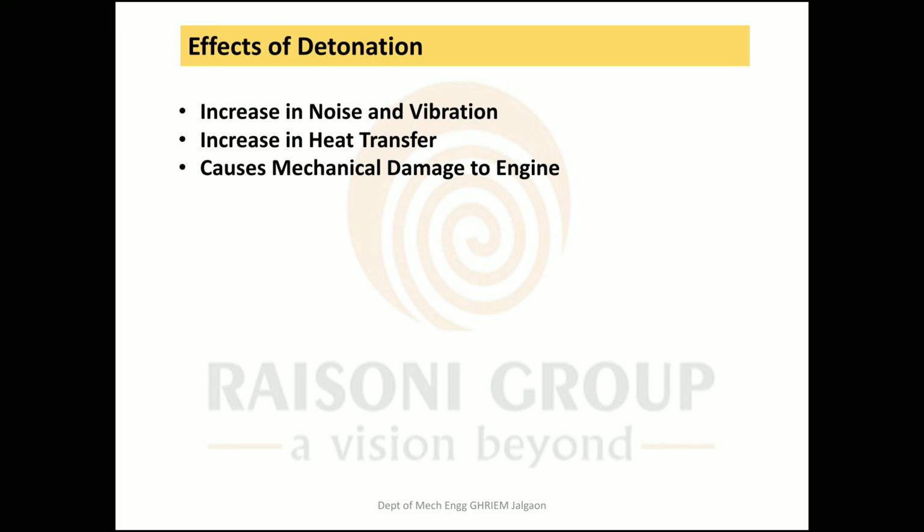The next one is pre-ignition. Ignition of the mixture by some hot surface within the combustion space before the normal spark ignition occurs is called pre-ignition. The detonation waves crossing and recrossing the cylinder cause a flow of the hot gases in and out of the spark plug cavity.